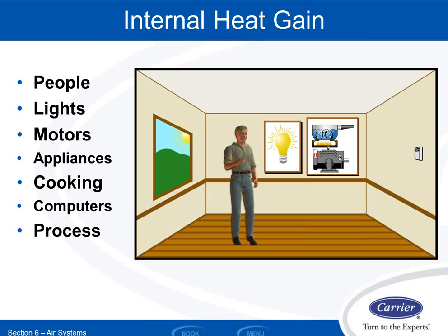So we have different types of heat gains and heat losses for the building. Right now we're showing internal heat gains. So that is where the building is picking up heat from, other than the boiler or furnace, obviously. But where else is it getting heat from? And that heat I might have to remove, especially in the summertime. So first off is the people. We already talked about that a lot last week. People generate quite a bit of heat, and we need to remove that heat from the space if we're going to try to cool this space down.